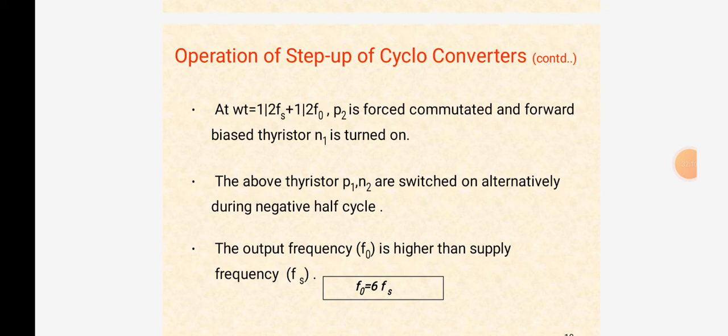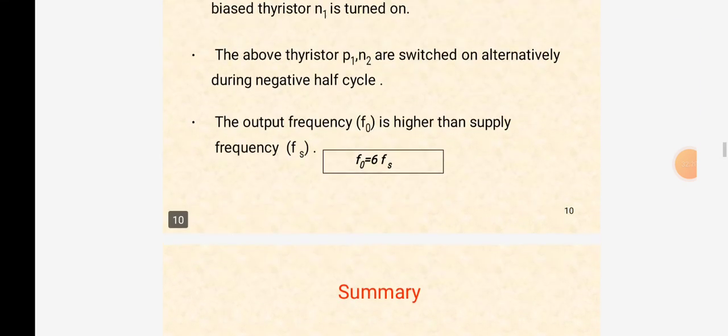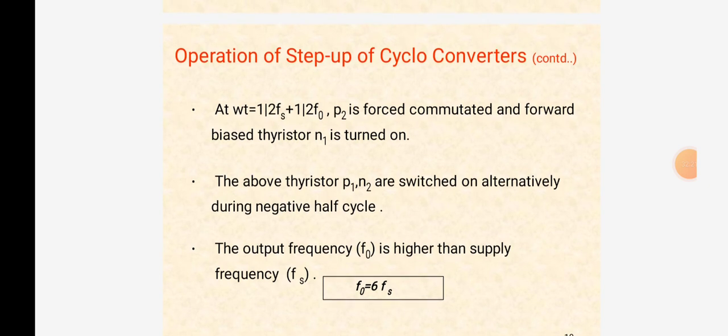And also here we have a few applications of cycloconverters. It is applicable to low speed and high power AC motor drives. It is used in HVDC transmission systems, in static VAR generation, and also in conversion of variable speed alternator voltage into constant frequency voltage in aircraft and shipboards.